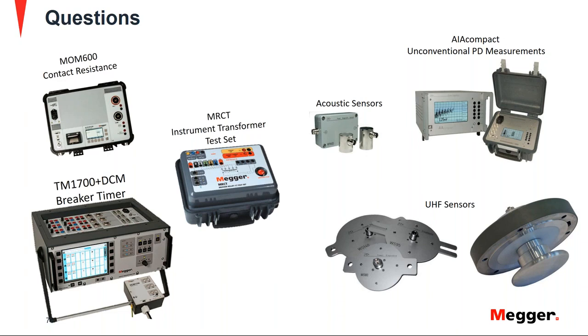You can see the use of ferrites very commonly in cables that we use daily, like the cables that connect your monitor to your computer, or the power adapter that you have for your laptop. They will have a little cylinder next to the connector. Those are ferrites, and they are there to filter signals or noise coming from whatever you are connected to going into your computer. So they are effectively a high impedance at high frequencies, but they are more like a magnet or a ceramic material instead of an inductor.